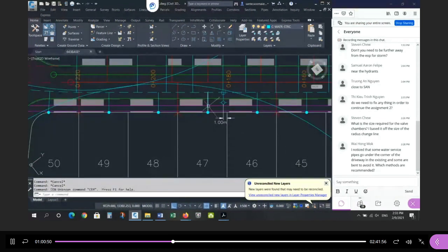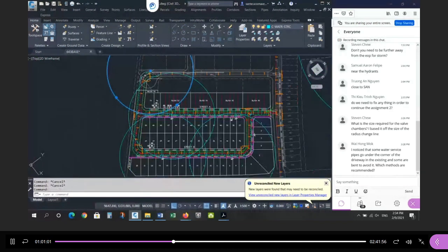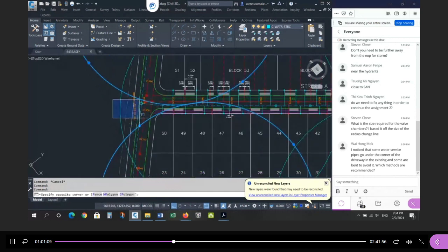So I'm going to draw a circle here. This is about the houses, not the roads. So I'm going to use this circle, 75, and you can see now I can fight the fire on the road from this hydrant all the way down to here. I can fight the fire on this section using this hydrant and this hydrant, and then this little wedge in here that's not covered by either of those two circles, we can use this hydrant. At the intersection, you'll be able to see this hydrant. I don't have to go around the corner. When you're in the intersection, you can see that hydrant.